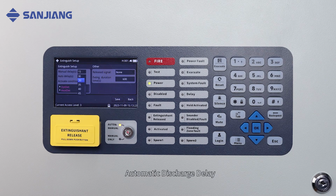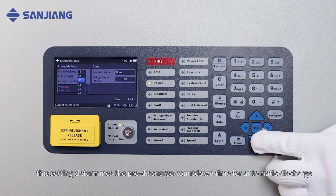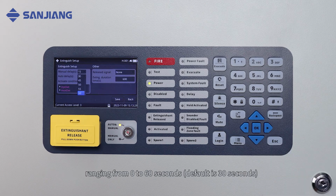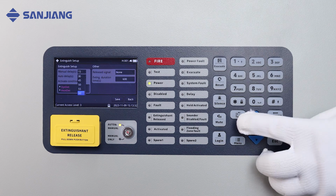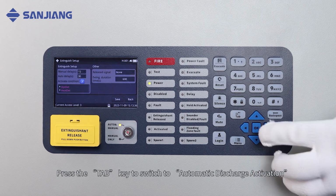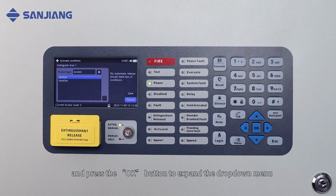Automatic discharge delay. This setting determines the pre-discharge countdown time for automatic discharge, ranging from 0 to 60 seconds. Press the Tab key to switch to automatic discharge activation, and press the OK button to expand the drop-down menu.